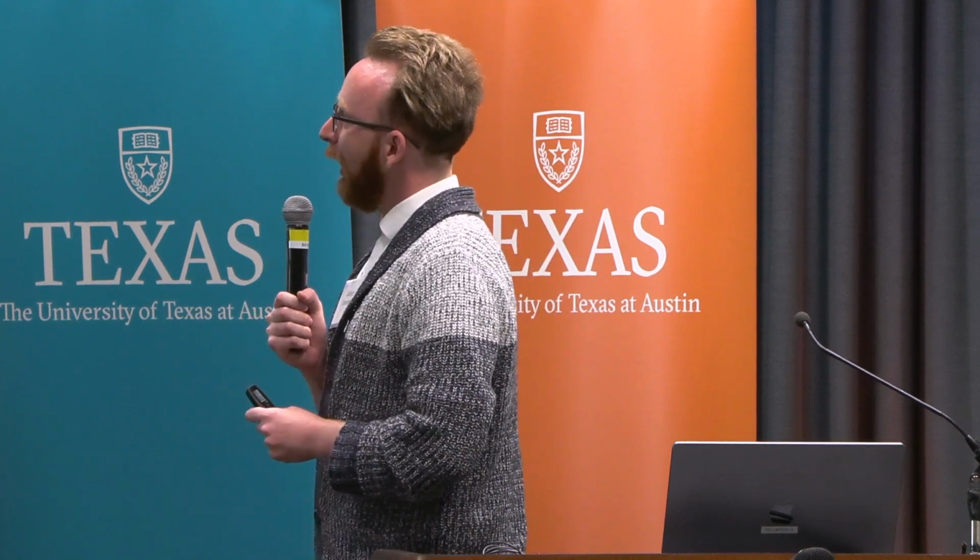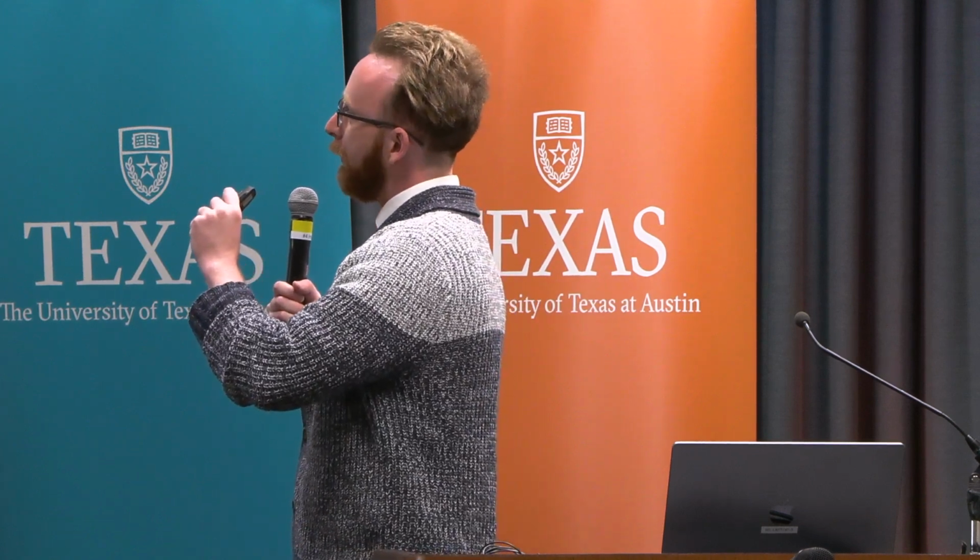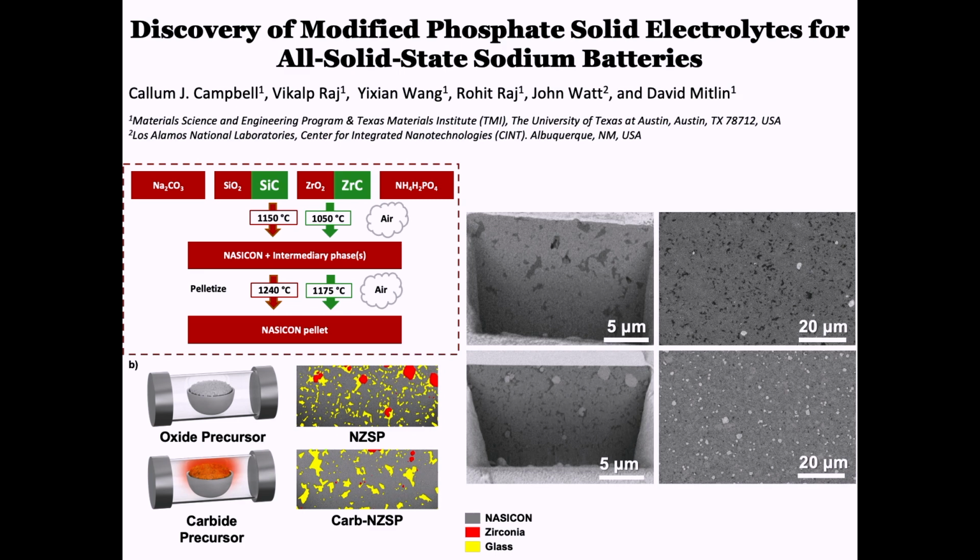What we did here really ended up working better than I expected, really better than any of us expected. We decided to take the traditional processing route, which would be to mix your powders, grind them up, fire them, grind them up again, and press them into pellets to get a nice ceramic compact. And this ceramic should be able to conduct sodium ions and act as the electrolyte in our batteries.